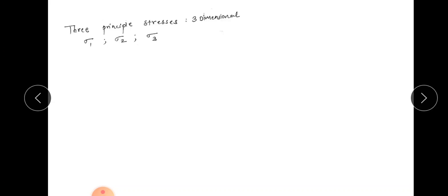Now already we have studied the principal stresses in strength of materials, and in the last video also I gave you the explanation about principal stresses and Mohr's circle construction as well as the formula associated with it. Now basically, what are principal stresses? First of all, let us understand what a principal plane is. A principal plane is a plane where the value of shear stress tau is 0, and the value of normal stresses like sigma x, sigma y, sigma z on that plane is a principal stress.